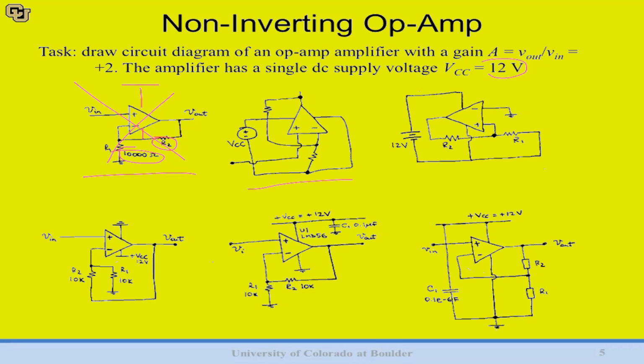The second attempt is obviously misleading. You can see we haven't labeled input, we haven't labeled output. Additionally, if we follow the data flow, we're going from left to top, which is very weird and non-standard. None of our components have either designators or names or component values on them, so we don't like this. Additionally, we haven't labeled ground. There's a lot of problems with that. Try to avoid that completely.